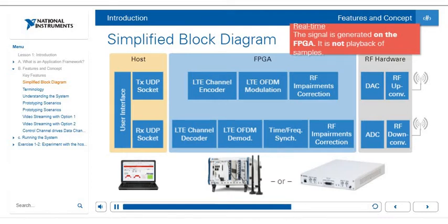In terms of hardware, the host is usually going to be a PC or a laptop, and the target will be either a USRP RIO or a FlexRIO plus an adapter module. The whole system runs in real time because the signal is generated on the FPGA. In other words, we're not doing playback of pre-recorded signals, but have a fully functioning real-time system.